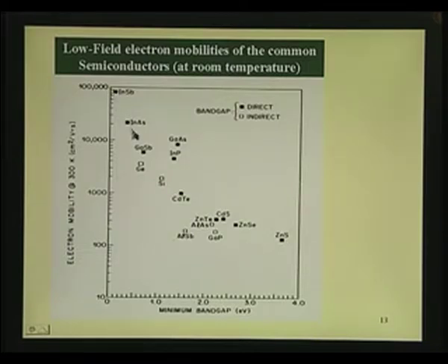So, you do not go and jump into that and say, I will take this indium antimonide and make use of it for making my high speed devices. If your high speed devices with that material have to work, what should you do? You must cool down drastically, because at room temperature itself you will have plenty of electrons, and junction will not work like a junction.